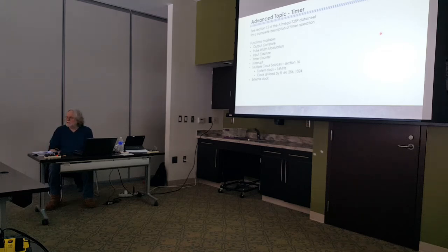Input capture is great if you're trying to measure how long is a DIT. You read the timer when the signal goes high. What you're really doing is the input capture register captures the value of the timer, because the timer's running at some fast rate versus how you're keying. And then you read the timer again when you release the key, and you subtract the two numbers, and now you've got the duration of that pulse when you're trying to decode Morse code.